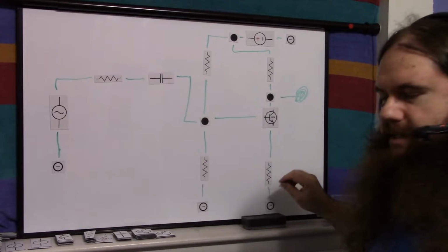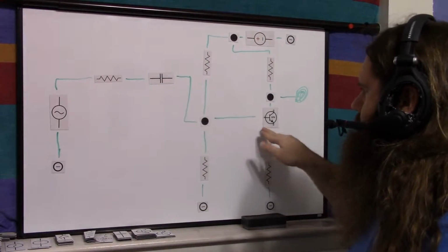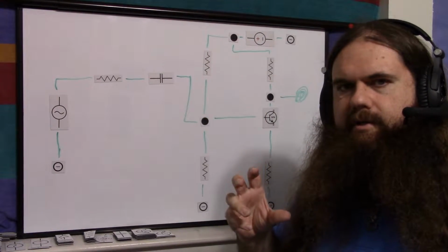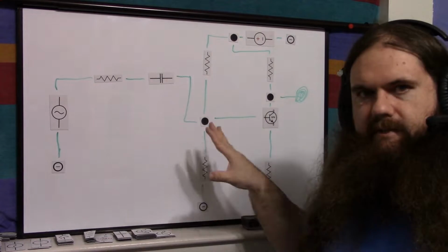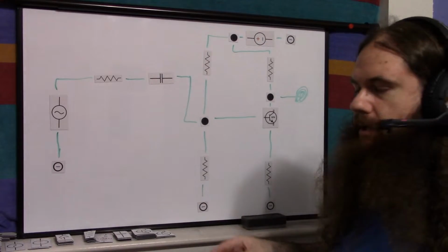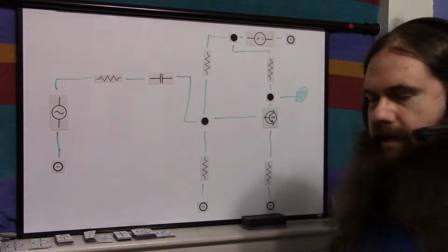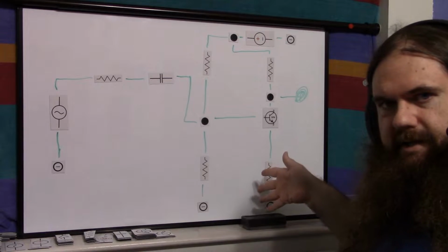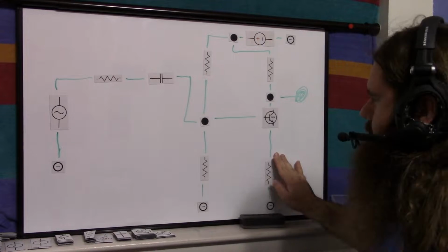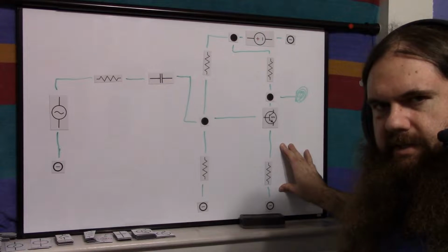If we think of this as a distance, what if we could just give it space without anything? Just plug the signal directly into the base and let the transistor move up and down within this margin without having to have this extra circuitry to do it. That is how the negative power supply works. Basically, you have the positive power supply doing all of this, and the negative power supply applies a voltage to this resistor so that when the signal is 0, the emitter is at the voltage you give this resistor directly.